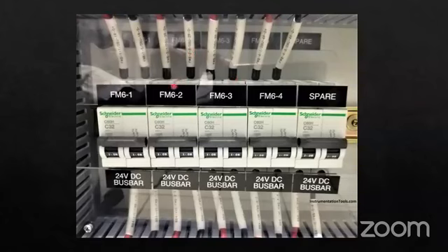Like if you can see here, this MCB FM62 will be having this ferrule. So that ferrule will also consist of the data of this MCB. You can see here FM621. So 1 and 2, that is how it is shown here. And then after the slash, you can see DBU, that is the target. So you can check any wire ferrules, and you can say, okay, this cable is connected through this MCB to any other field instrument or whatever. So that is cross ferruling.